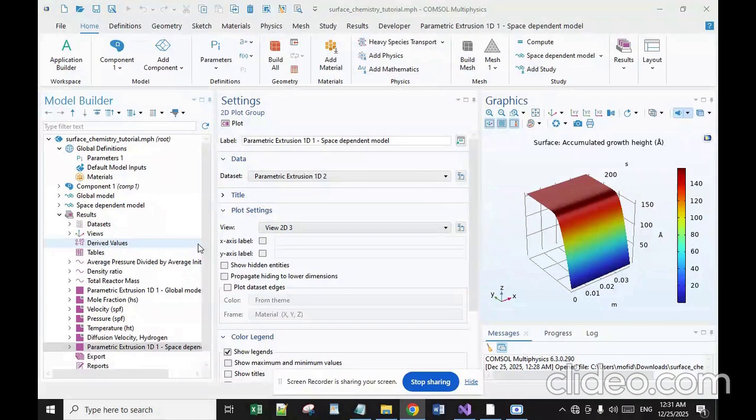The first step is vapor introduction. Volatile precursor gases containing the elements for the film are introduced into a reaction chamber. The next step is surface reaction. These gases reach the heated substrate where they break down, decompose, or react chemically. The next step is deposition. The desired solid material forms a thin layer on the substrate surface. The next one is byproduct removal. Volatile, unwanted byproducts are carried away by gas flow.